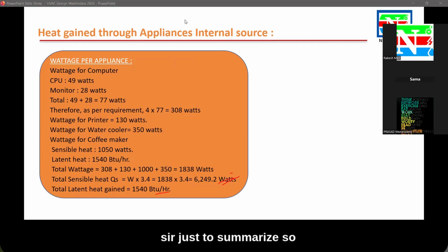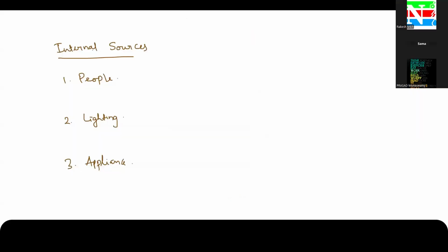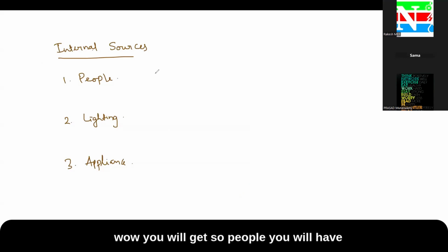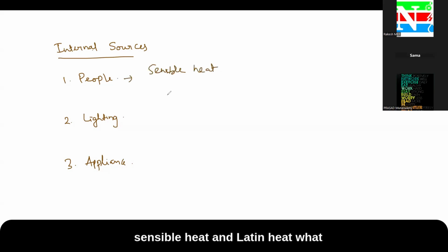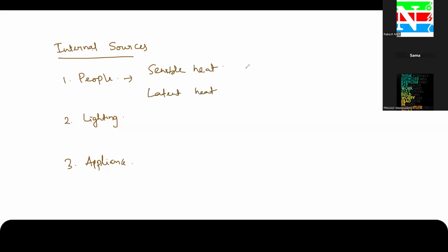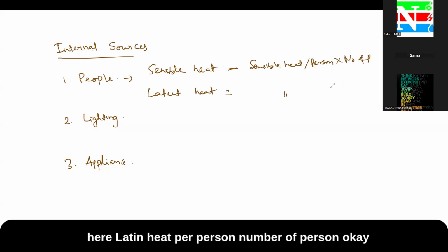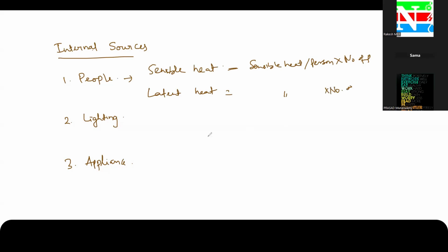Yes, sir. Just to summarize, people will have sensible heat and latent heat. What is the sensible heat per person, multiplied by the number of persons. Similarly, latent heat per person times the number of persons.